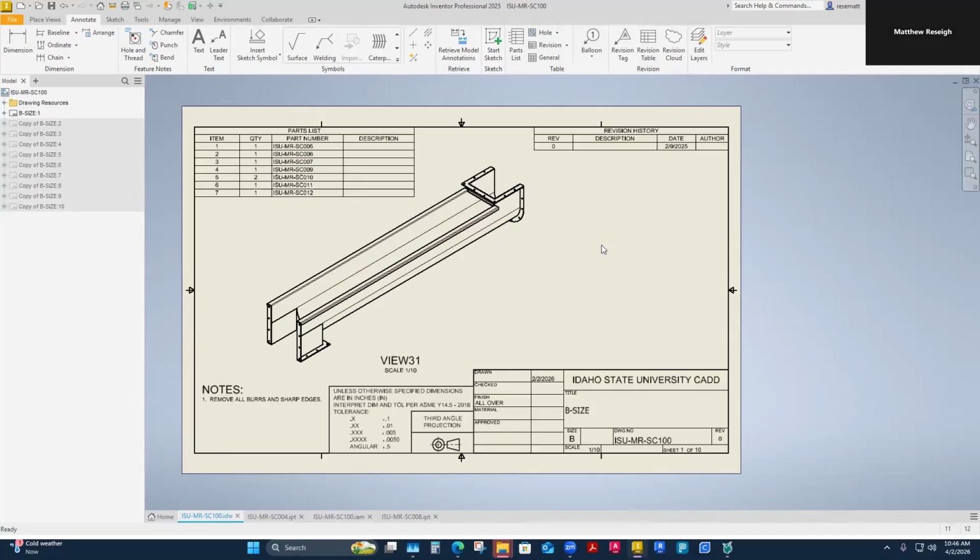But between inlet and discharge, filling it full of potato and having some compressive force on these sides of 12 gauge, if I just put some U-shaped ribs, they help maintain the integrity of the sheet metal from inlet to discharge. And they give me a place to apply mounts, maybe to mount this to the ground or something. So I can use those ribs and stiffeners to bolt on feet. I'm going to have to hold this conveyor up somehow.